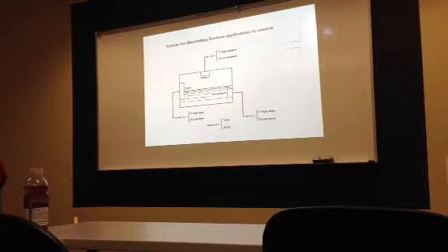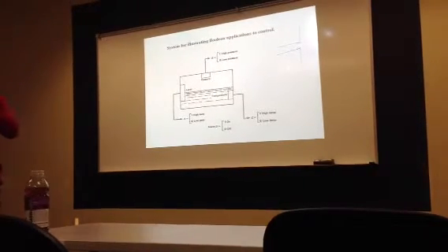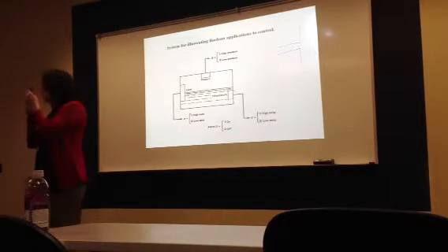We work with what's called in digital a Schmitt trigger. Below a certain level, it's off. Above a certain level, it's on. And in between, it latches to where you came from. So if the error is less than 0, you turn off. If the error is greater than 0, you turn on. And we call it on-off control versus continuous control.